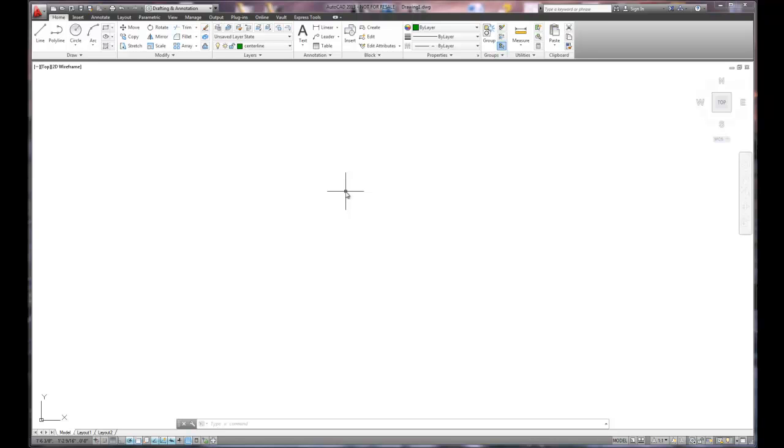In architectural drawings, many times center lines are used to locate the center of the walls or doorways or openings like windows. And so in our case, what we're going to do is draw a vertical center line to indicate the center of our doghouse and to help us align the elevation of the doghouse also. So we're going to draw a line. We'll pick a starting spot here on the screen. We're going to point straight up, and we're going to draw a line approximately 10 feet long.